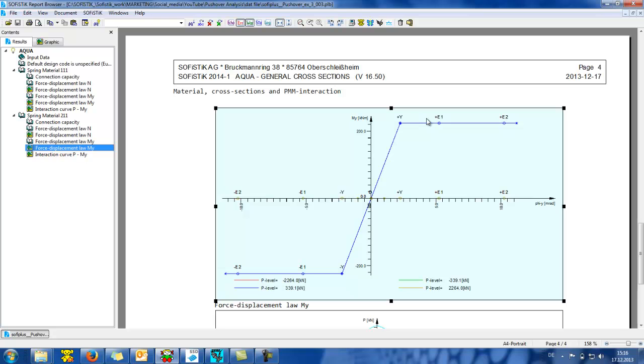Those are the performance level labels that I have already defined in my workflow in order to control and simplify the evaluation of the hinge reaction. So my first interval is from 0 to the yield point, and then I give two more points in the bilinear diagram, both for compression and for tension.